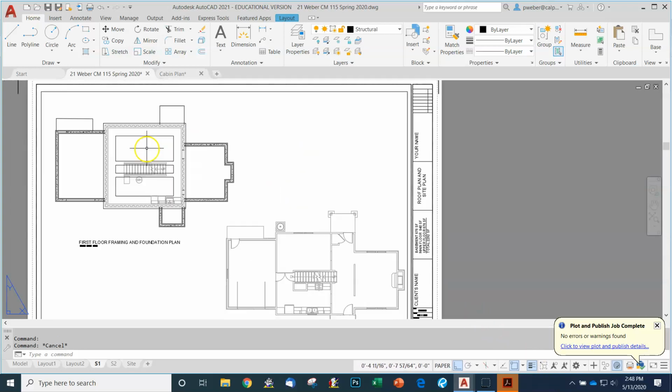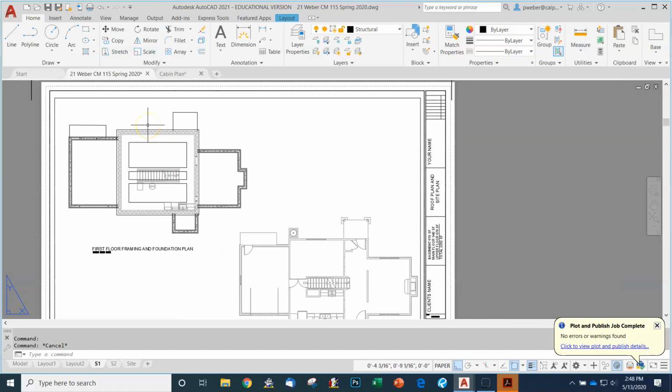And once again, we're in paper space. These should have been dashed lines. Let's type in LTS and change it to 0.3. So now we see our dashed lines in paper space. Okay, but I'm going back to model space to do dimensioning. So let me do that.